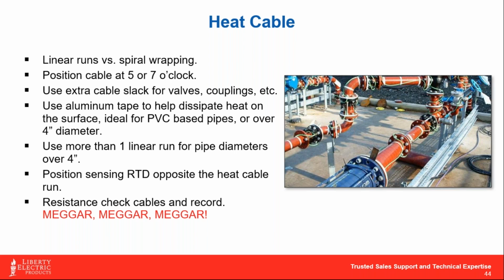It's a great way to ensure that your install is going to be successful by just testing that cable and ensuring that there are no ground fault interruptions. Unlike a process heater, you don't have to put a process heater on a GFI rated circuit. I think some facilities do it for safety reasons, and that's a good thing. But heat cables do require you to be on a GFI circuit. So we want to make sure that no voltage is leaking to ground when we install these systems and cause nuisance trips. So again, that's what the Megger is going to help you prevent right there.